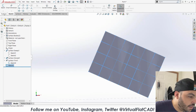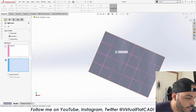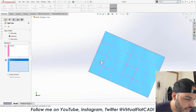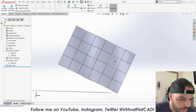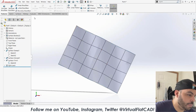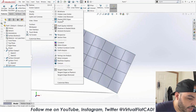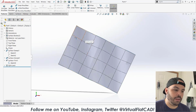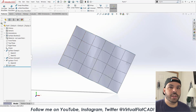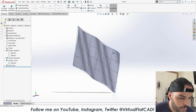So we have that. I'm gonna go ahead and split. I might actually have to split after I thicken, but let's see. So we have that. So now we have this checkered pattern. Let's go ahead. I'm going to change my view. Whenever I have split lines, I like to set my tangent edges as phantom. That way it's easier for me to tell what's an object line and what's just me splitting the surface into multiple pieces for one advantage or another.